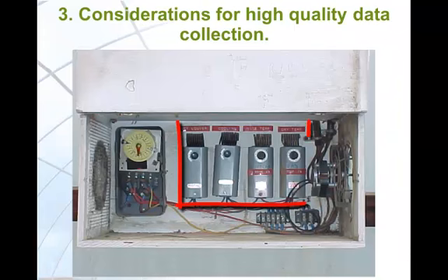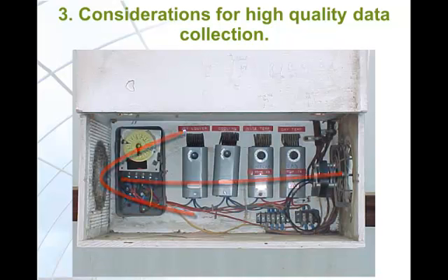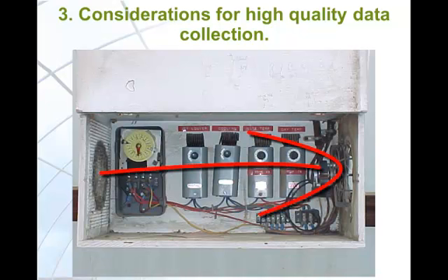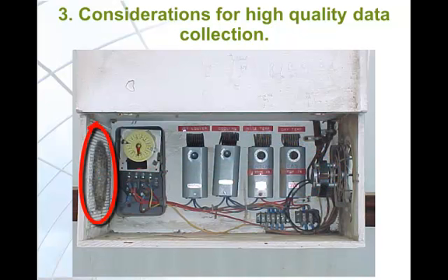This box shields the thermostats and aspirates them with a fan. It is important to consider here the heat the fan motor generates. If the air is moving from right to left, then the heat from the fan is being pushed into the box. That is not good. However, if the air is moving left to right, then the heat from the fan exits the box. That is good. Dust should be cleaned from the mesh on the left side of the box.